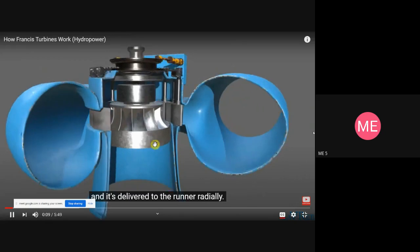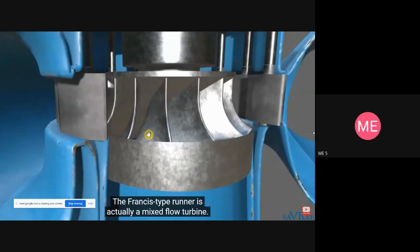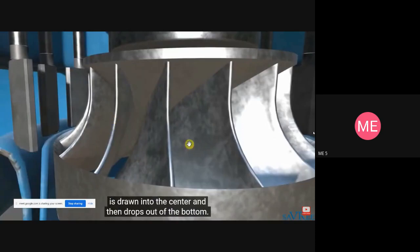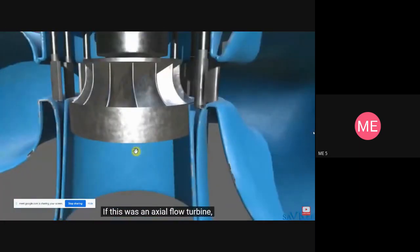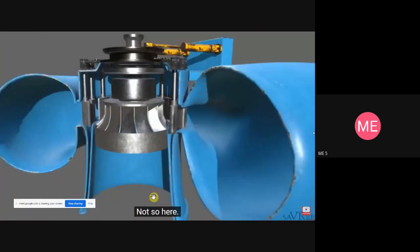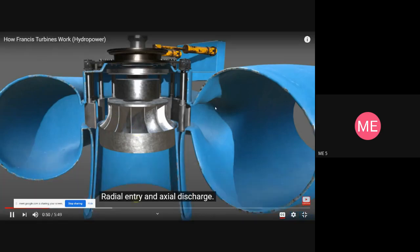It's delivered to the runner radially. The Francis type runner is actually a mixed flow turbine. The water is allowed to enter radially because it comes in from the sides, is drawn into the center, and then drops out of the bottom. Compared to an axial flow turbine, there's quite a lot happening. If this was an axial flow turbine, it would just flow in from the top, go straight through the runner, and drop out the bottom. Not so here. We're using radial entry, where we are flowing to the center of the runner, and then dropping out of the bottom in an axial manner. So that's why we call it mixed flow. Radial entry and axial discharge.